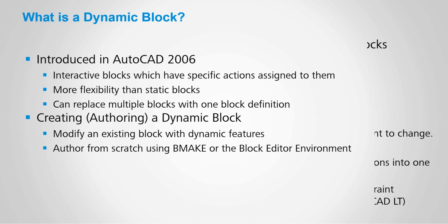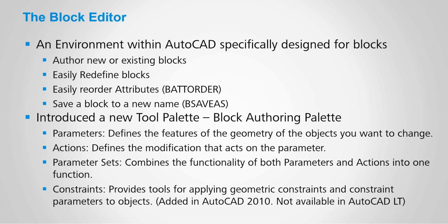So first of all, just to talk about the block editor. Again, it's an environment within AutoCAD. It looks like you're in AutoCAD, except the tools have changed. And again, we can author new or existing blocks. One of the nice things about the block editor is that it allows me to easily redefine a block, to update it. And this doesn't have to be a dynamic block. It can just be a regular AutoCAD block.